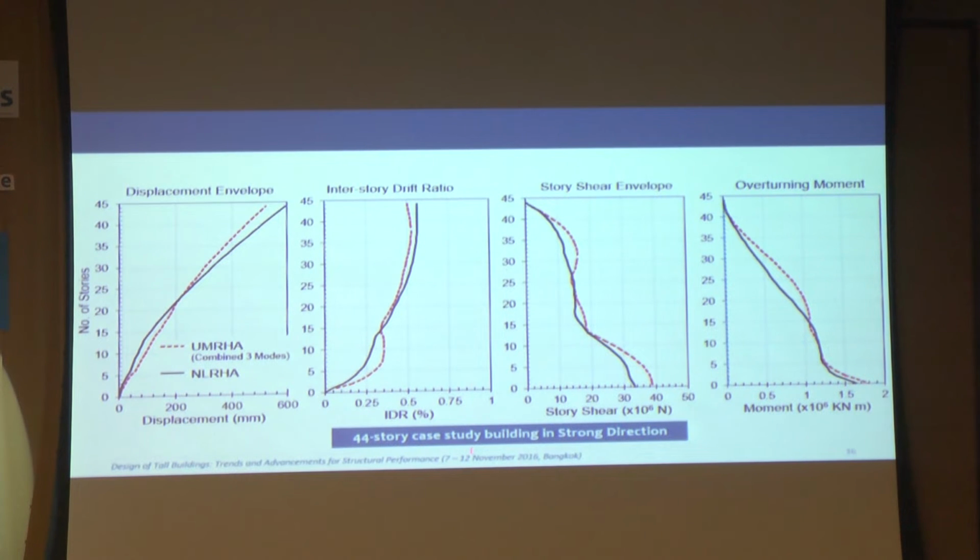It shows that the complex response of that 44-story building can be described by just three modes, 3 single degree of freedom systems, 3 lollipops. You just come up with 3 accurate modal properties, and you can get approximately the same response as the time history result of that 44-story building. But the beauty of this modal separation is not that it gives a result equal to time history analysis. This is not its beauty.